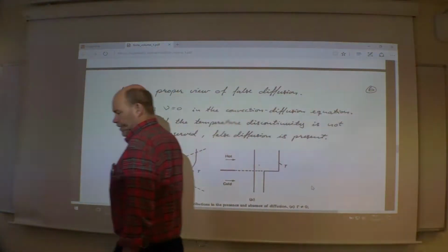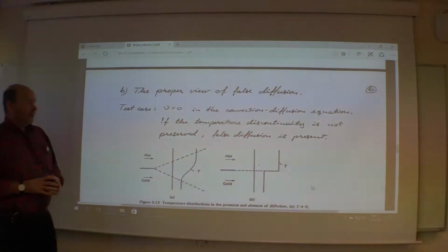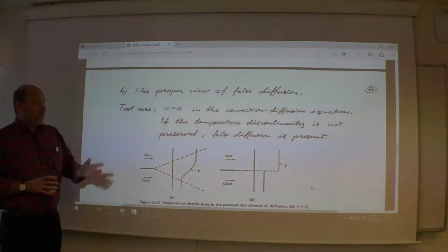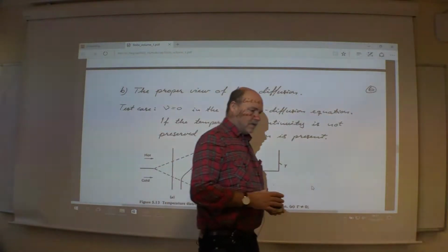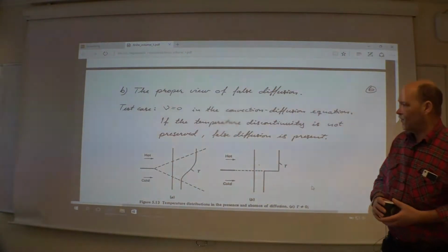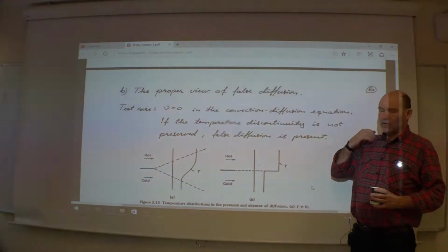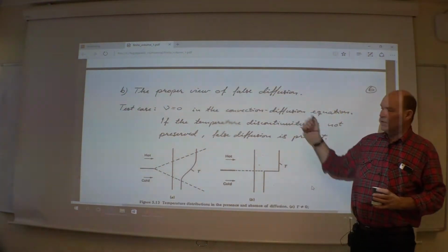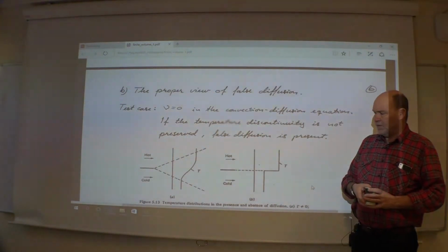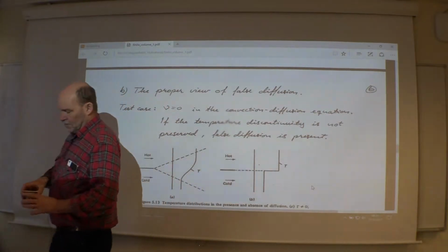Now, this one here is taken from Patankar's book, and he addresses this additional diffusion. Of course, he admits that yes, a first-order upwind scheme is very diffusive. Now, he didn't like the word that other people were using about his programs, saying that it was a lot of false diffusion. So, if you can recall, I named them the two diffusion mechanisms.